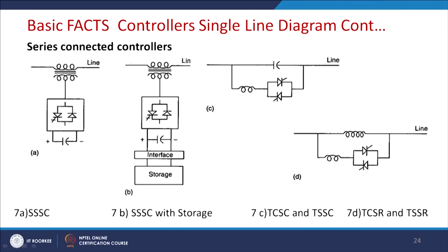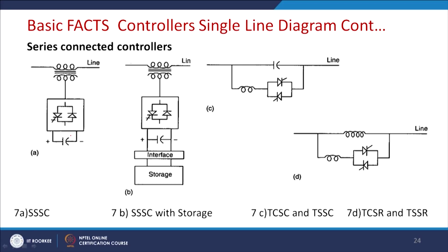Now let us consider the FACTS device which is basically the SSSC. It is a series controller. So again it is the same as a STATCOM, but it requires a series injection, and ultimately it can also have a current source converter topology, but it is not very popular. For this reason the voltage source converter topology has been shown here. In the same way this SSSC can come with storage devices, so it can inject voltage and current in phase and quadrature, and it is quite a versatile device as far as series compensation is concerned.